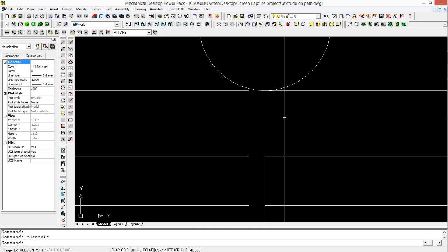Now think about your 3D printer, for example. If you were trying to 3D print an object that you swept along a path, and you left a gap less than the resolution of your printer, say your printer is printing at 1/10 of a millimeter. Well, if your path was open less than 1/10 of a millimeter, wouldn't a 3D printer go ahead and print over it? It would print right past it. It wouldn't even recognize it as a gap. But the drawing would know there was a beginning and an end for the sweep.